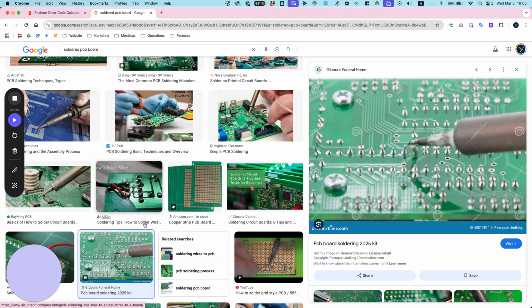So even though there's a break right here, let me double check here. I'm pretty sure these aren't connected, but now I'm not exactly sure. Okay, they're not connected. So this is actually a break, whereas these are just spaces. They're still connected underneath, okay? You see how I did this? I'm not exactly sure, but we use the multimeter to check.